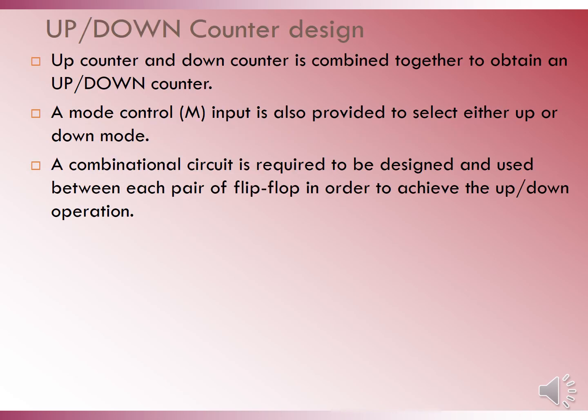In case of up-down counters, we are going to use an extra input which we call the mode control bit. That mode control bit gives us an option to select whether we want to count up or go in the reverse mode, that is in the down mode. For this, we require an extra combinational circuit which will be designed and used between each pair of flip-flops in order to achieve that up-down operation.